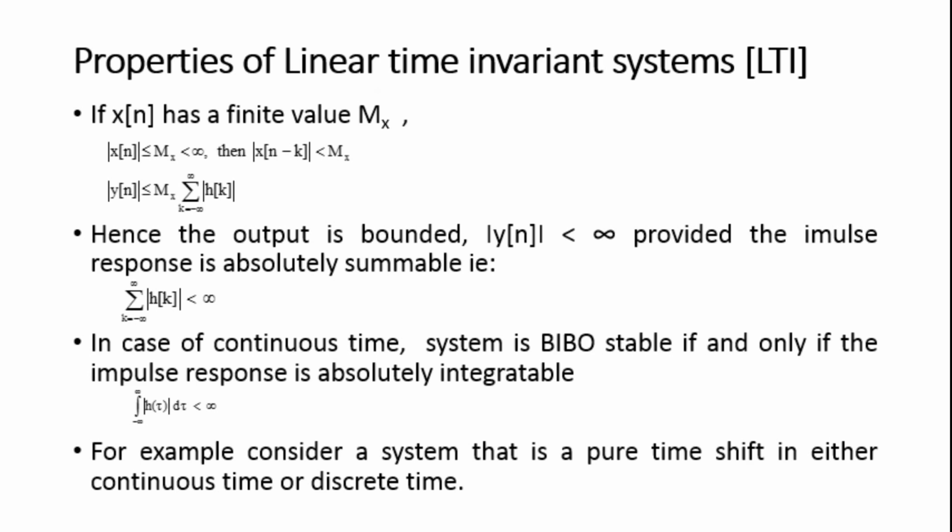In case of continuous time, the system is BIBO stable if and only if the impulse response is absolutely integrable. That is, the integration from minus infinity to infinity of |h(tau)| d tau is less than infinity.